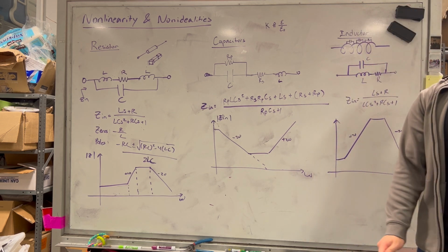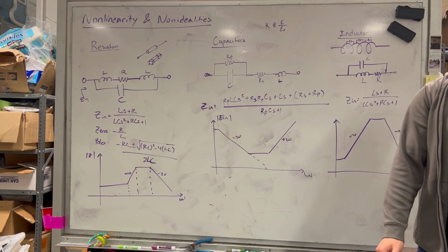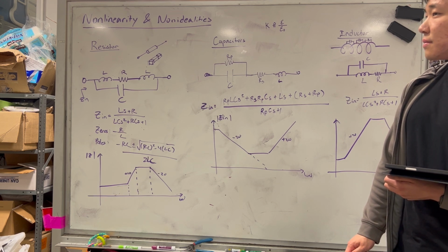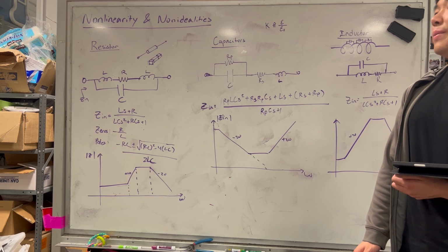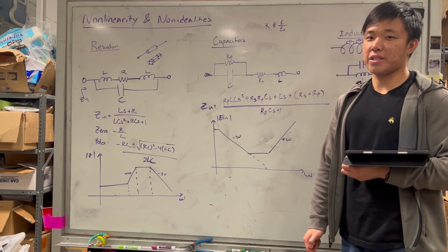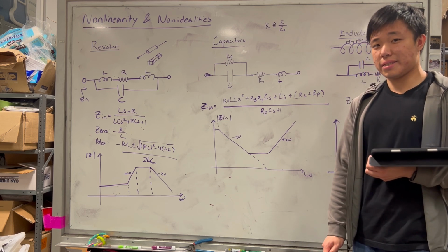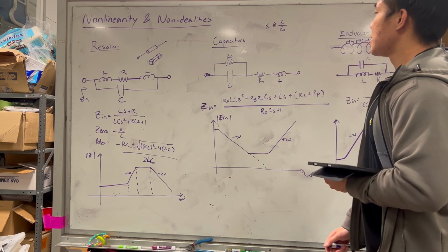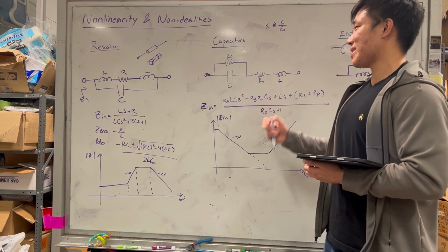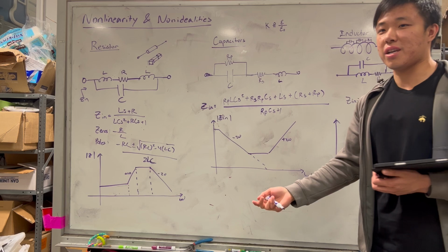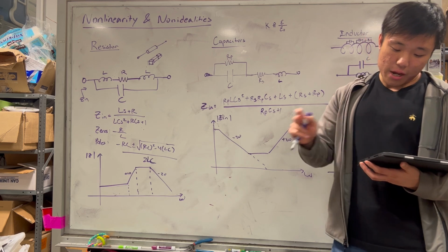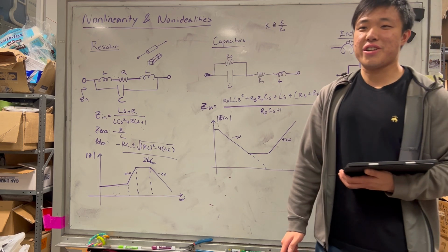Go ahead. Like, the amount of area you need changes based on the K, to have the same capacitance. Let's say I have maybe 1 micron cubed to work with. If I have a higher K versus a smaller K, what happens to the value of capacitance? It goes up. Yeah. So you can think about K as how dense this capacitor is. The higher K you get, the more capacitance you get for the same amount of thickness between the plates. Now, there's always a trade-off in engineering.